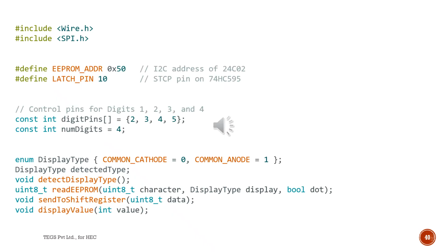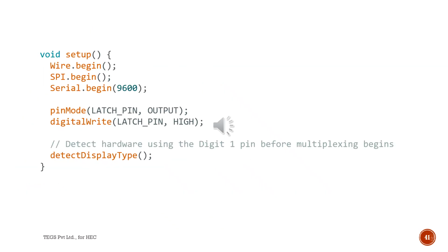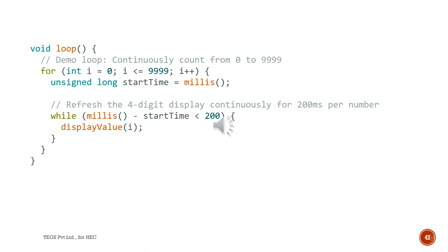This is the first page of the code. Here the libraries, pins, variables, constants and subfunctions are initialized. This is the second page of the code. Here the once-executable setup functions are defined. Initializing Wire begin and Serial Peripheral Interface begin is initiated in this section.